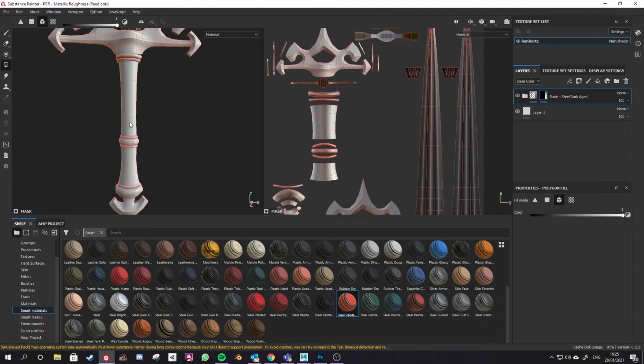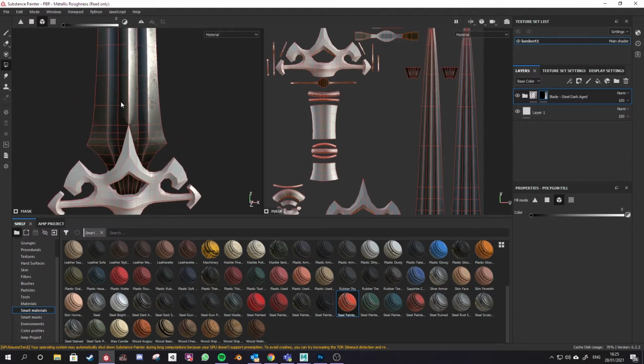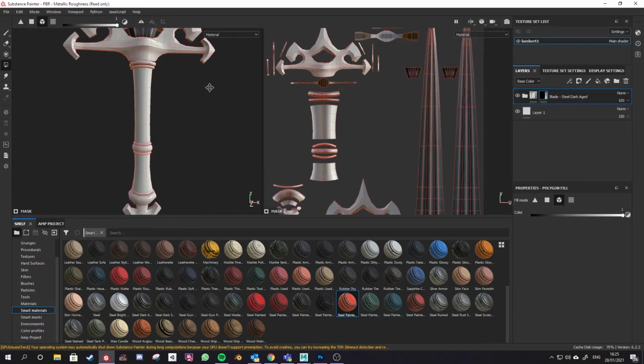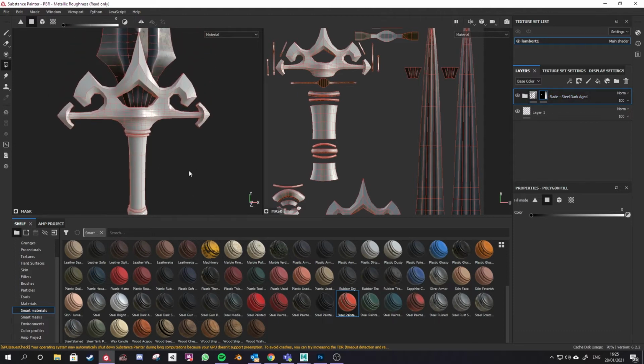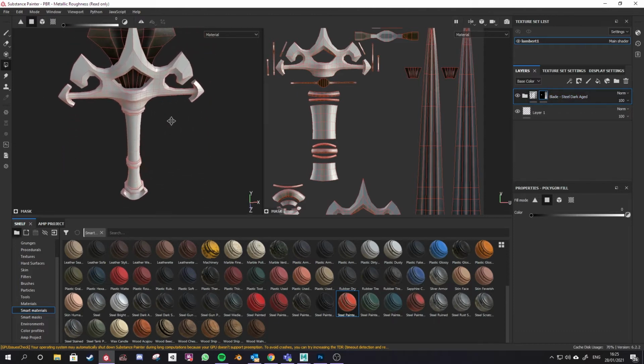If you press X, you'll go from painting black to white, and I can then go and paint out things again. So X switches color for what you're applying to the mask. You'll see here when I've got the polygon selection, I can drag across polygons that I want to reveal, and then again I can press X to change it to black again, and I'm blacking out that mask. And if you take a look at this mask on the right hand side here, you can see what we're doing. We're applying white onto the areas that we want to punch through our black mask, just like we would if we were applying this in Photoshop.